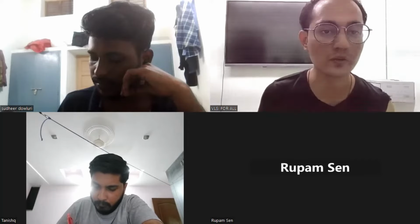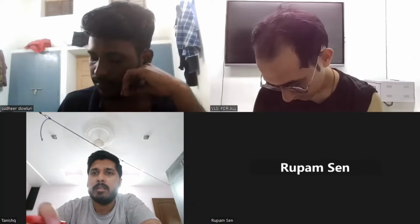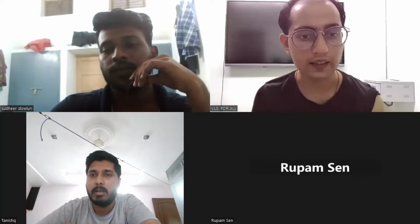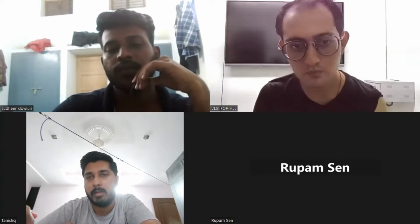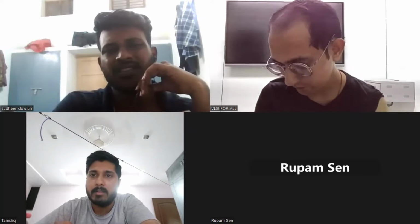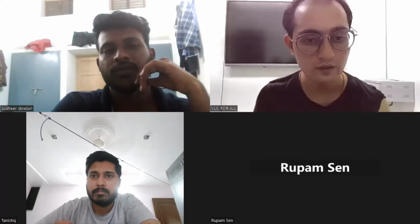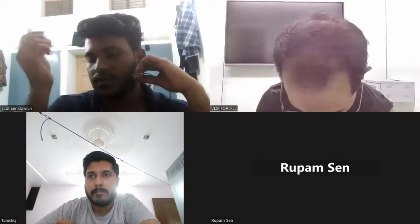Okay. So the disadvantage of SR flip-flop. The condition 1-1 creates a problem and has to be avoided, because when S and R are both given the input 1-1, the output continuously changes and is not stable. So that is the disadvantage, that it cannot accept the input 1 and 1. Okay, fine. This is an invalid state, I will say. Unknown invalid state.